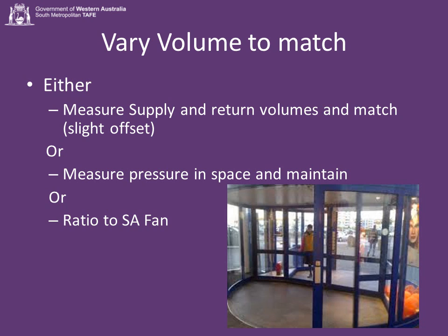If you get it wrong, either you end up with a negative pressure or you end up with too high a positive pressure, then you're going to get trouble with the doors and windows, especially revolving doors. The revolving door will start turning like a wind turbine, and they can build up quite a lick of speed. So we need to maintain a very slight positive pressure.